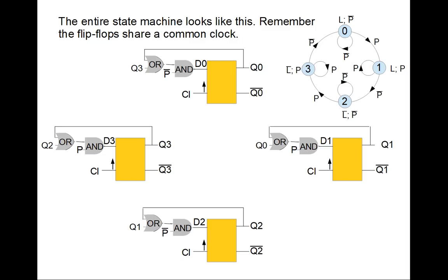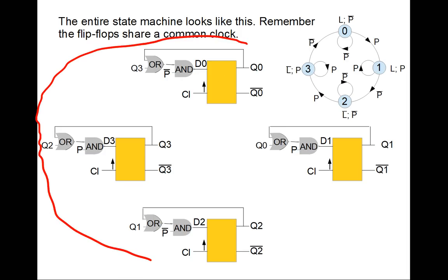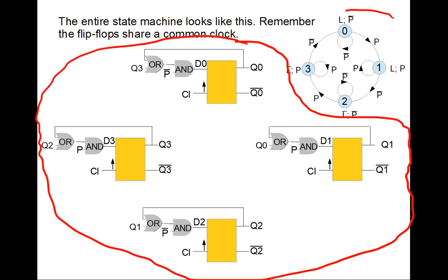I hope you figured it out. It's almost a pattern that you can come through, so that the entire state machine can now be represented in this form. So we have the ORs and the ANDs, and everything looks pretty good. Actually, these 4 circuits, when combined, would implement this state machine, which is quite cool. The state will go from this flip-flop to this flip-flop, and then return to that flip-flop. So it's kind of cool.